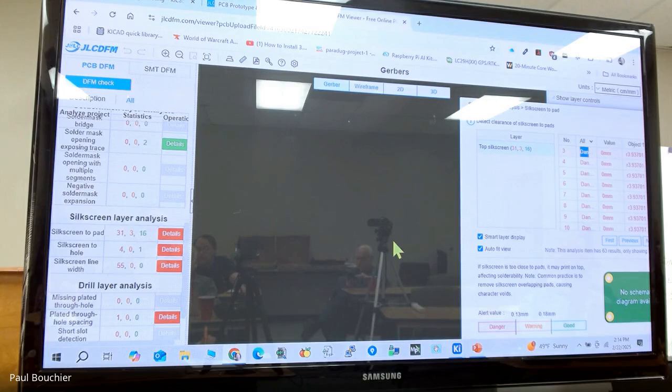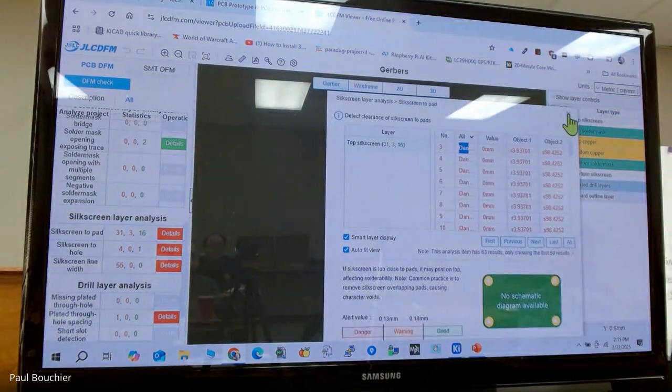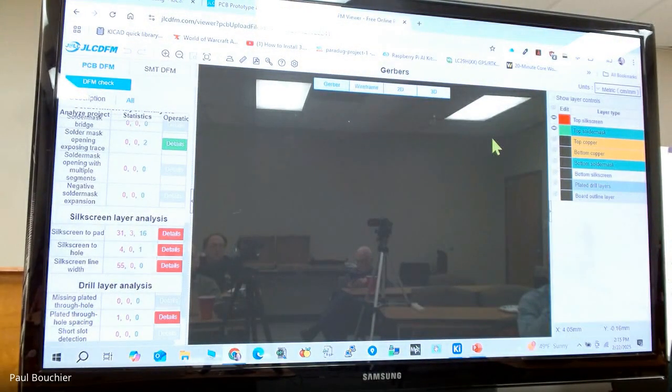When you're dragging the footprints around from that initial big block, it's very easy when you select to miss one of the silk screen layers. So you end up with a silk screen over here and a footprint over here. When you highlight the part, you'll see a blue line through it and you can move it back over. But it's easy, when moving parts around, to not select the whole footprint. Anyway, this says it needs some work. That's what we wanted to find out.